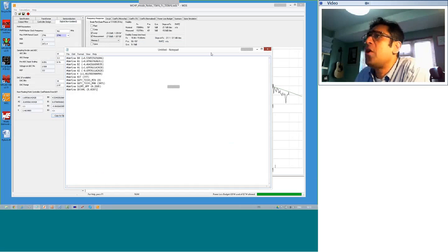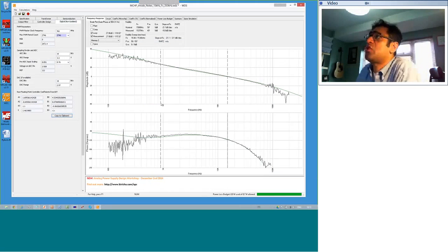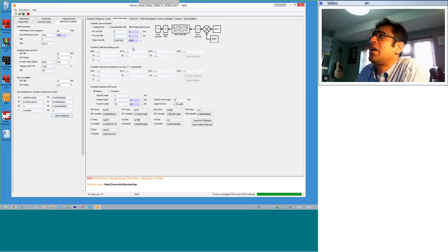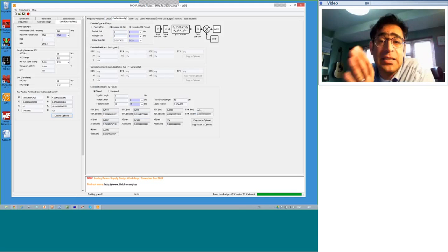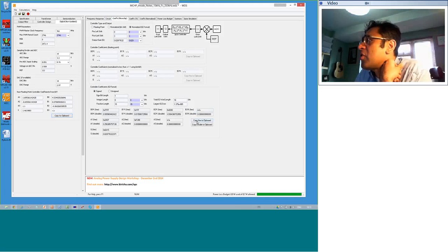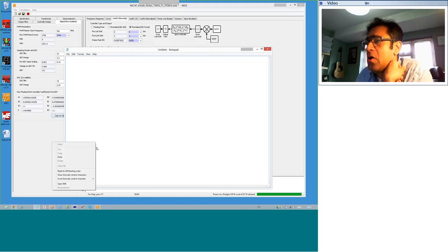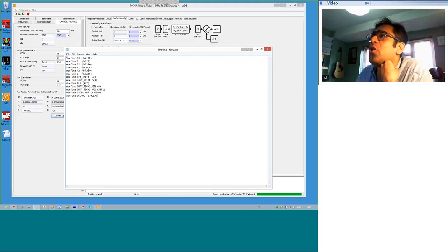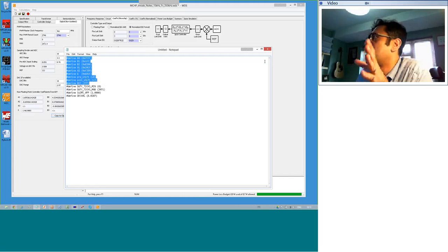If you don't have a floating point because it's expensive and you're going for a fixed point processor, we've got a microchip tab, and here you can do lots of number manipulation. This is fixed point. Again, WDS will automatically align all the numbers for you. Again, you've got copy hexadecimal to clipboard, and you go paste. These are your coefficients. These are the bit shiftings that you need to do. That's your reference. This is all nice and easy for microchip.